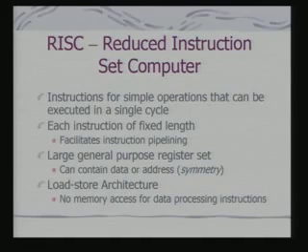Arithmetic as well as logical operations for a RISC processor always involve registers. So, the operations always involve registers and not memory locations directly. Once you have performed the operation, the data is stored to the memory, so you have store instructions, and before performing an operation, data is loaded from memory, so you have load instructions. That is why RISC architectures are also referred to as load store architecture.